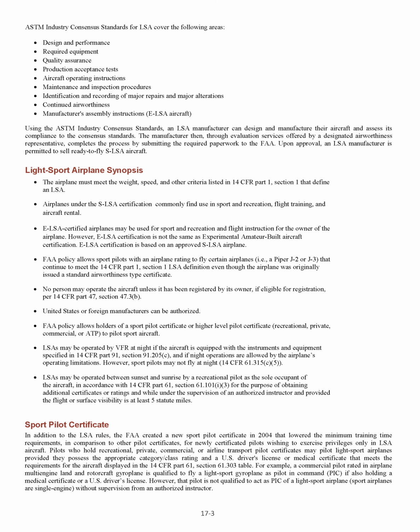provided they possess the appropriate category/class rating and a U.S. driver's license or medical certificate that meets the requirements for the aircraft displayed in the 14 CFR Part 61, Section 61.303 table. For example, a commercial pilot rated in airplane multi-engine land and rotorcraft gyroplane is qualified to fly a light sport gyroplane as pilot in command, PIC, if also holding a medical certificate or a U.S. driver's license. However, that pilot is not qualified to act as PIC of a light sport airplane.